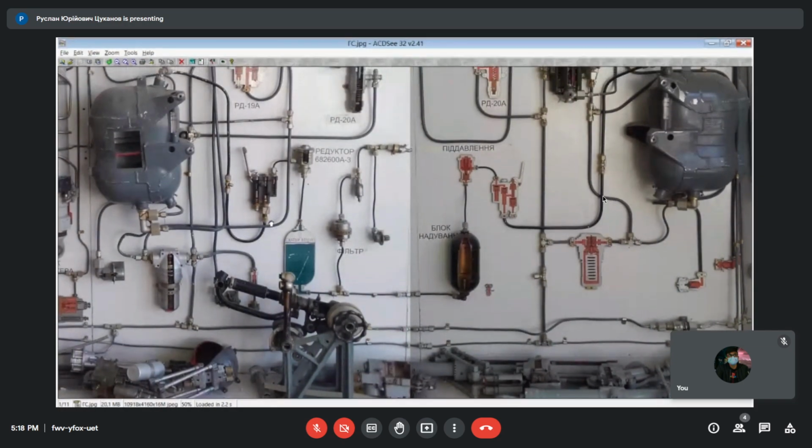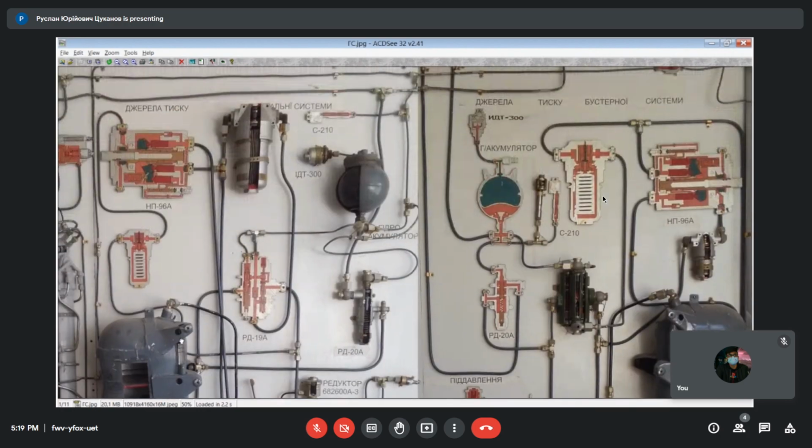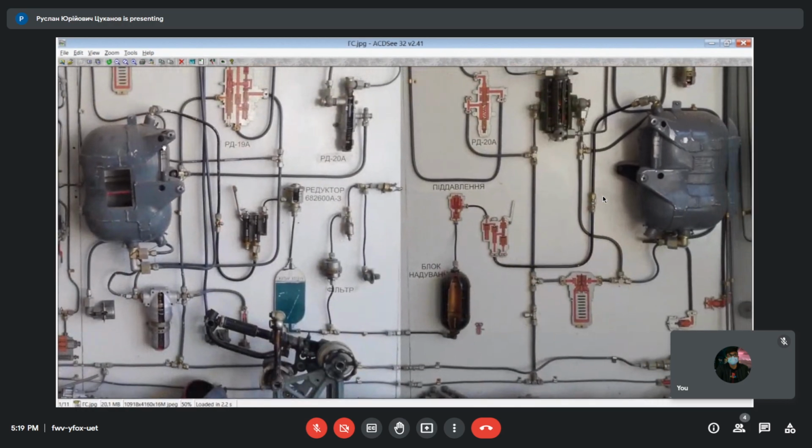Next, from which side of this pressure relief valve pipe, black, you see the hydraulic overpressure lines are of black color, so air inside, and this black line comes to the hydraulic tank. This is the hydraulic tank of the combined hydraulic system, and this is of the power control hydraulic system. So here another pipeline goes to the hydraulic tank. Hydraulic tank structure we will discuss next time.